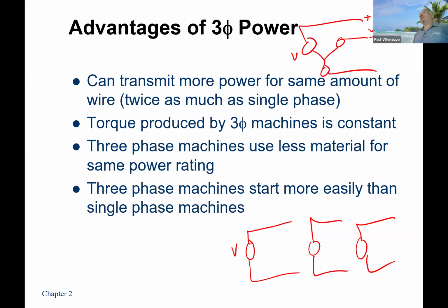By the way, I would be willing to bet that none of you in this classroom have three-phase power at your residence. Anybody here does? If your folks or you know somebody who has a really fancy wood shop at their house, maybe they would, but they're paying a heck of a lot of money for that three-phase connection, because the utility won't even run you three-phase unless you can prove you've got enough demand or enough load. If you don't, sorry, you're going to be running 240 volt. That's what we're going to give you. You have to prove that you're going to get three-phase.